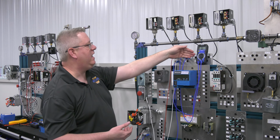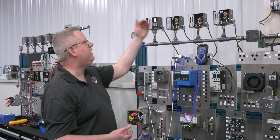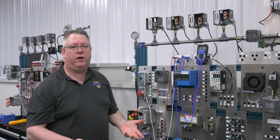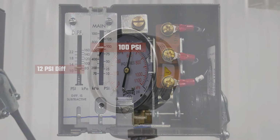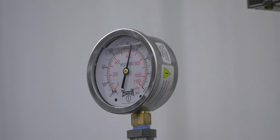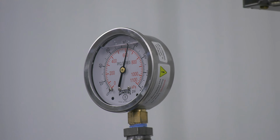Now I've got a multimeter here just set to beep when we go over pressure to shut the boiler down. So I've got that set for 100 psi with a differential of 12 psi, and let's just see how close they get today. Oh, and I broke at 95 psi.